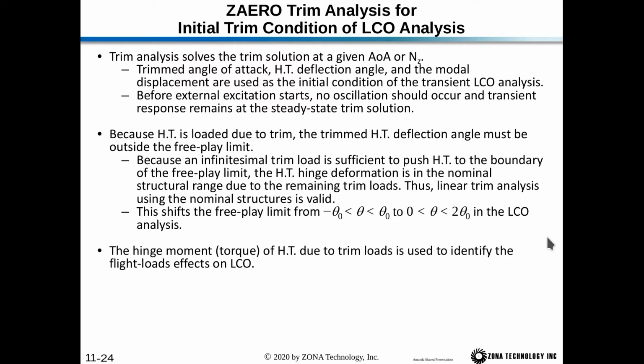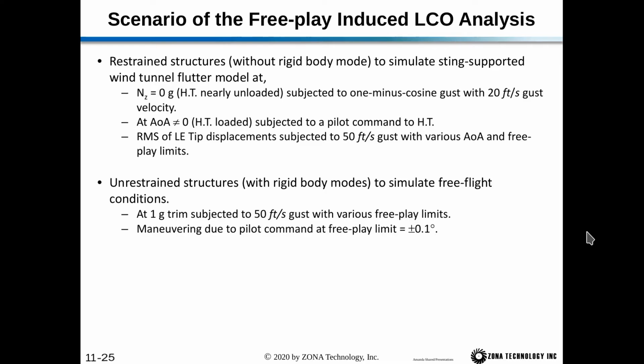And the hinge moment of the horizontal tail due to the trim loads is used to identify the flight loads effects on LCO. And we'll have two scenarios here for the LCO analysis. The first is the restrained structure without rigid body modes to simulate a sting-supported wind tunnel flutter model at NZ equals 0 Gs, where the horizontal tail is nearly unloaded.